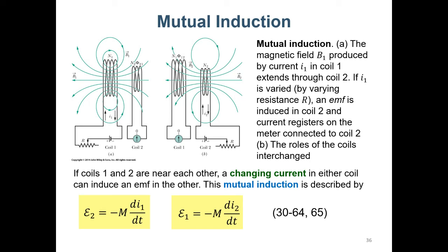And in this case, this is an inductor, so it will generate some magnetic field, and this magnetic field is changing before it reaches the steady state. So in this case, the magnetic flux of this coil will be changing. And according to Faraday's law, this changing magnetic flux will generate an induced EMF for the second coil.